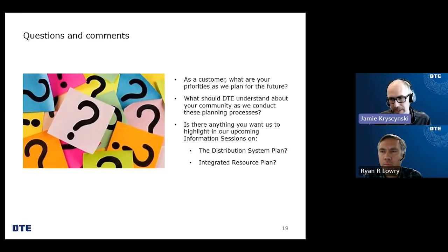So this is a pole top maintenance and modernization program. We are making a much more significant investment in that over the next 5 years. And so that will again be going out and testing our poles, looking at the cross arms, the wires, insulators, looking for cracked or defective pieces of equipment that are going to cause problems, perhaps in the next storm or a future storm.